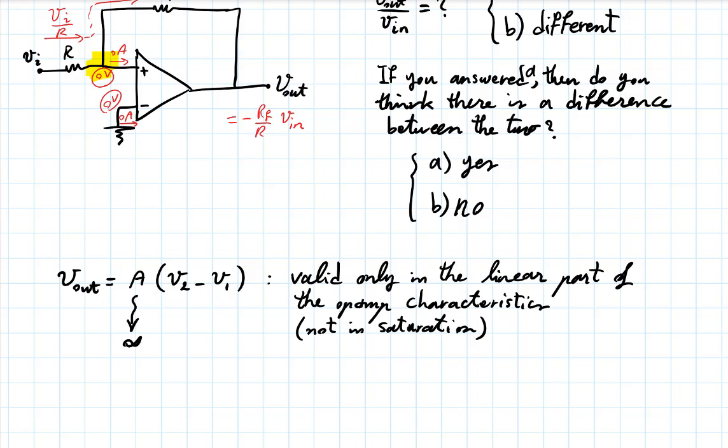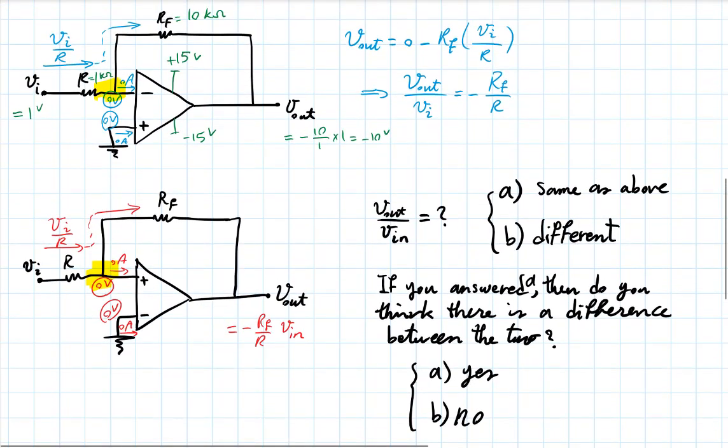If the voltage on the positive node increases momentarily, the output increases. Now that increase in the output, again through this resistive connection, is fed back to the input and reinforces the increase at the input. But then through the op-amp itself, the output will go further up, which then will further reinforce the increase at the input.